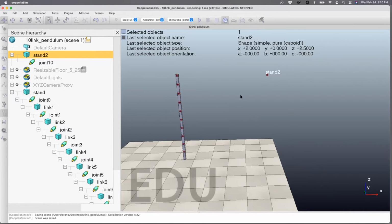Now the question is, how do we close the loop constraint? So here's where you need to use what is known as a dummy. I need to put a dummy at the end of link 10, and I also need to put a dummy at stand 2, sorry, at the joint 10, and then I need to tell CoppeliaSim that those 2 points should connect.